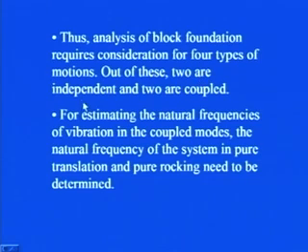So, you have 2 independent and 2 coupled motions for the analysis of block foundation. For estimating the natural frequencies of vibration in the coupled mode, the natural frequency of the system in pure translation and pure rocking need to be determined, right.